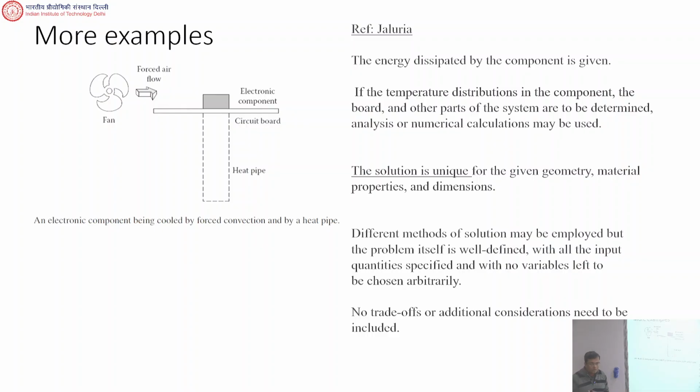Okay, so there what should we look at? We should look at the optimum design situation and choose the one which maybe gives you the minimum cost or something like that, as long as it meets less than 80 degrees Celsius. If up to 80 degrees Celsius it works fine, then we will not like to reduce it to 50 degrees Celsius, because that is like an overkill.